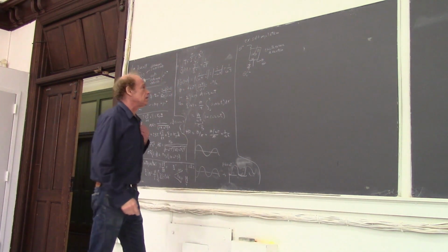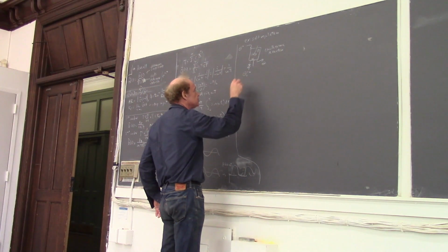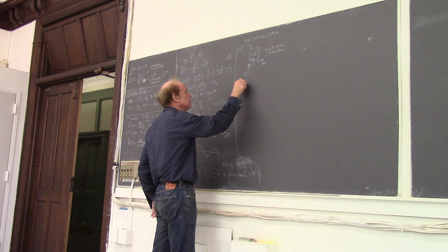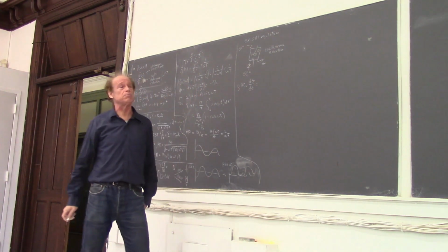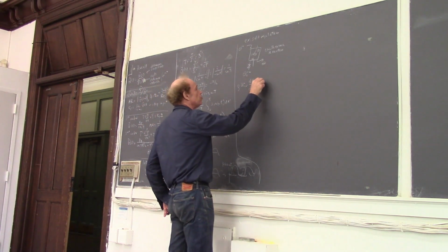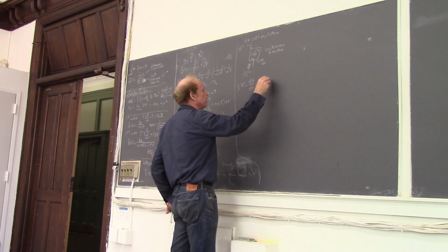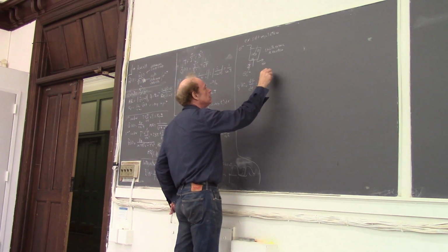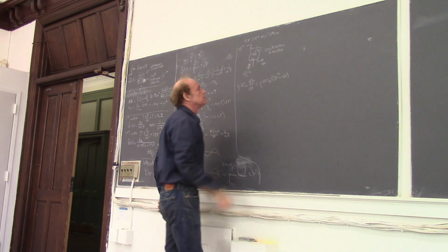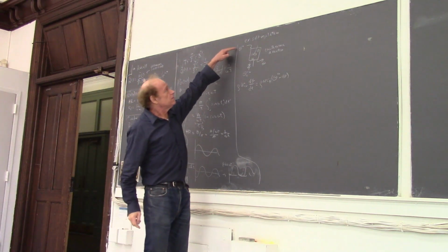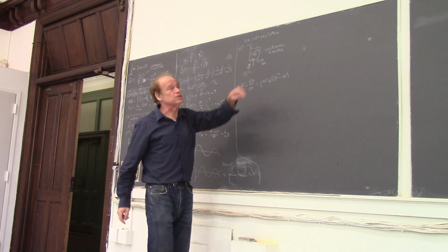So I can write for the temperature here, rho V CV, d theta dt. So the accumulation is in minus out. So I've got rho times the volumetric flow rate times Cp, theta in minus theta. So that's theta in being flowed in, theta out flowing out.